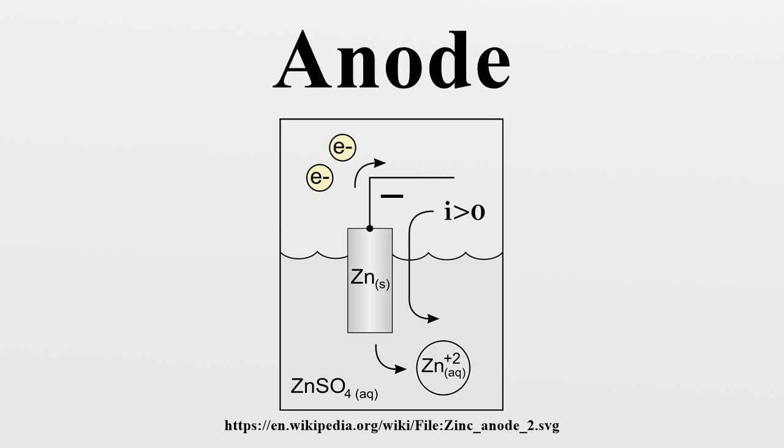Sacrificial anodes are particularly needed for systems where a static charge is generated by the action of flowing liquids, such as pipelines and watercraft. Sacrificial anodes are also generally used in tank-type water heaters. In 1824, to reduce the impact of this destructive electrolytic action on ships' hulls, their fastenings and underwater equipment, the scientist-engineer Sir Humphry Davy developed the first and still most widely used marine electrolysis protection system. Davy installed sacrificial anodes made from a more electrically reactive metal attached to the vessel hull and electrically connected to form a cathodic protection circuit.